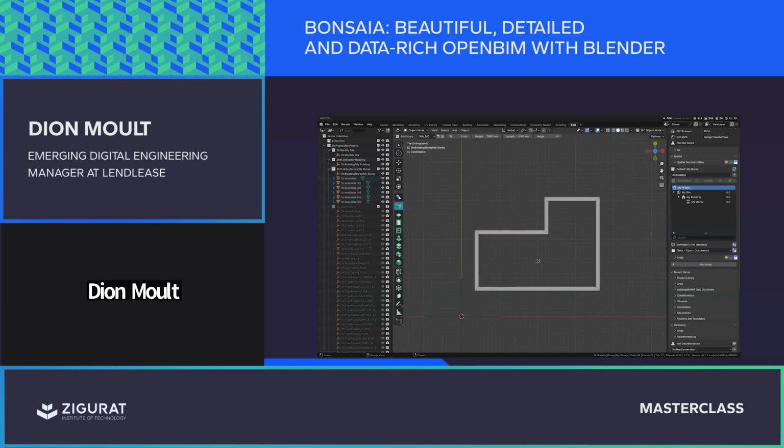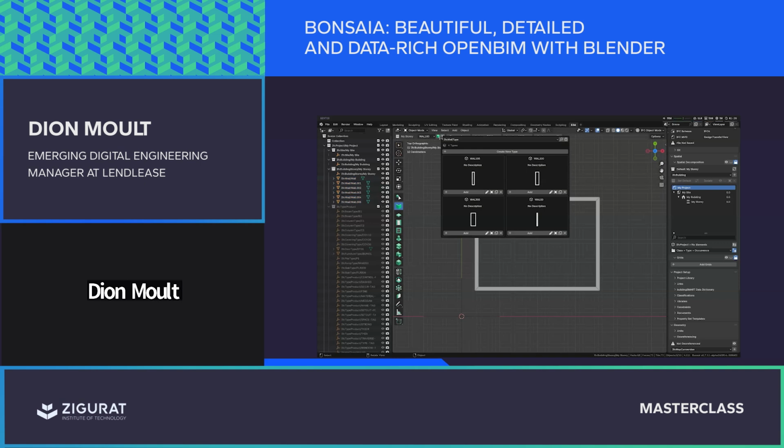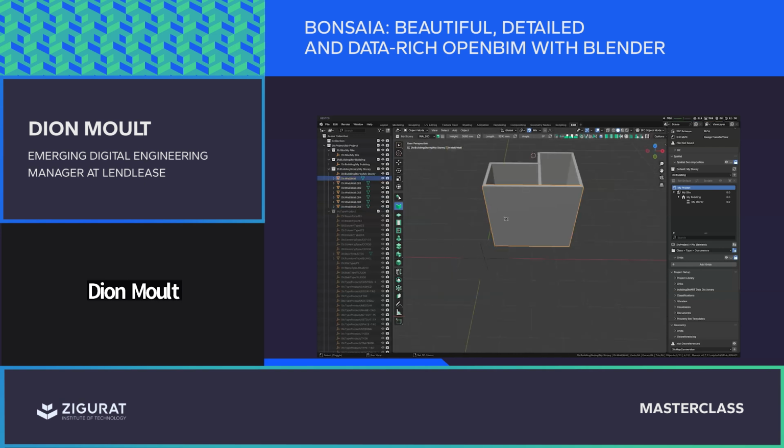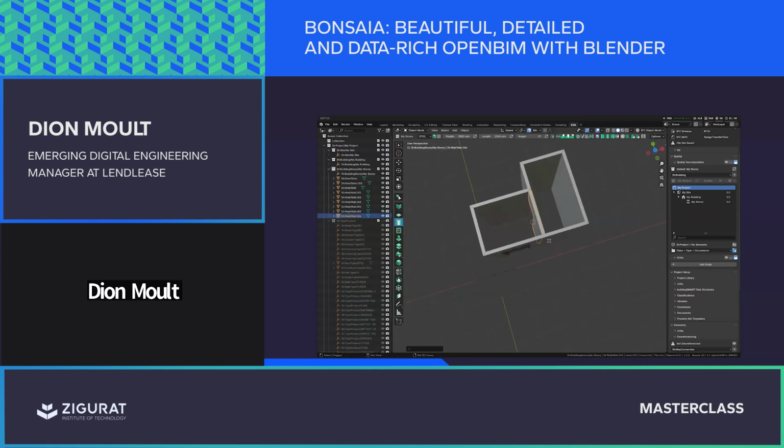So there we go. We've drawn in a bunch of walls. I've got a bunch of wall types already loaded in, so I'm drawing it with a 100 thick wall. I can put in a 300 thick wall over here and draw over here. Oops. Let me turn on some snaps. There we go. Let's line that up over there, and let's throw in a door. I've got one door already loaded in here. Maybe a door in there as well.